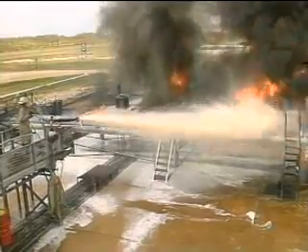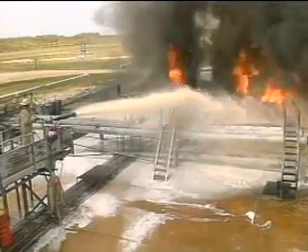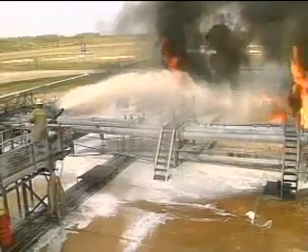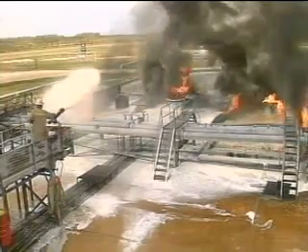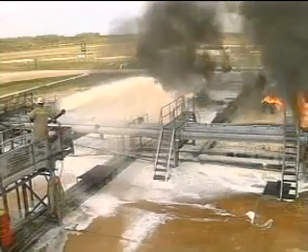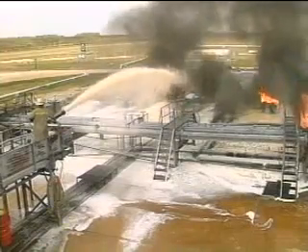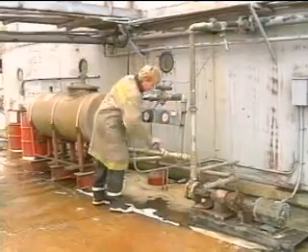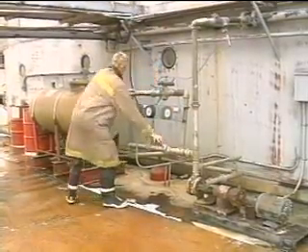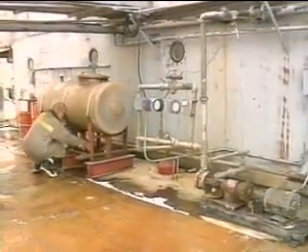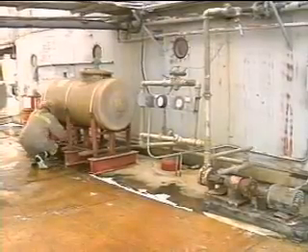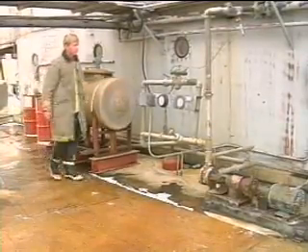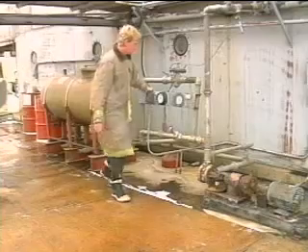On some ships, fixed foam systems may be of the balanced pressure proportioning type, which allows the foam pump discharge pressure to provide proper proportioning over a wide range of flow demands. In most cases, several valves must be opened and the pump started for the foam system to operate. Since time is so critical in a fire emergency, pre-planning is essential, and every person on the team must know his role.